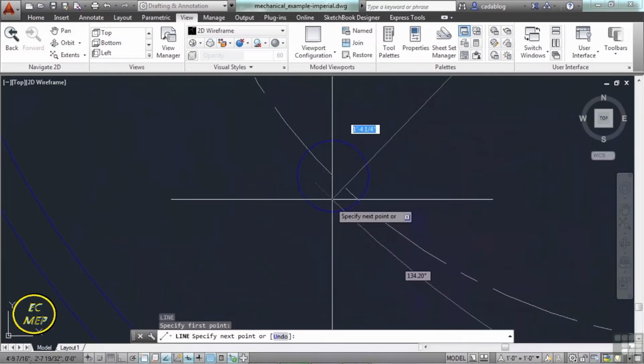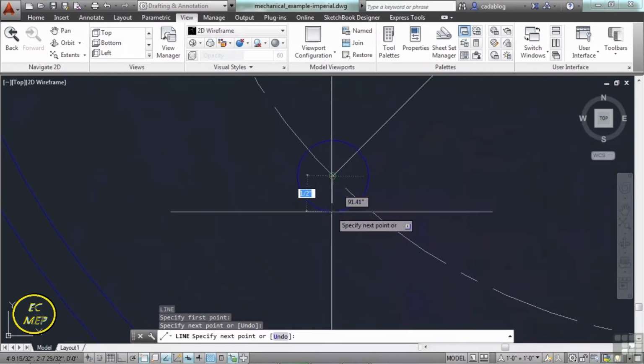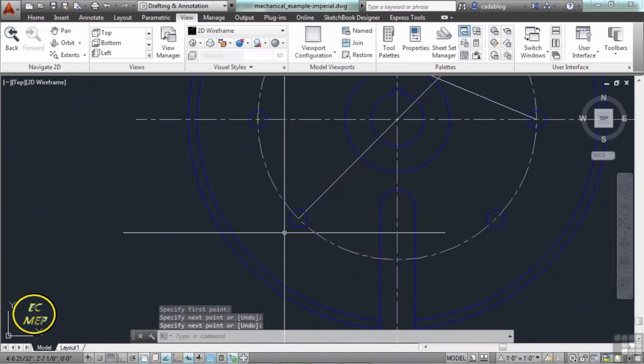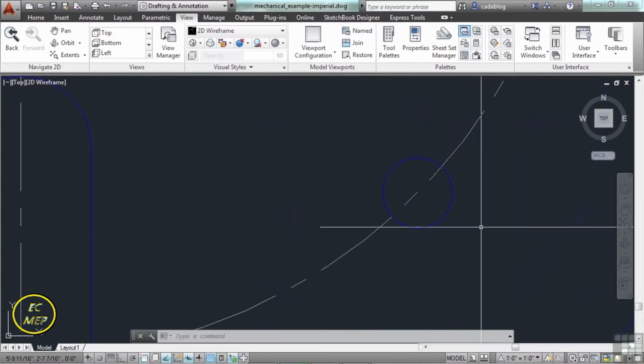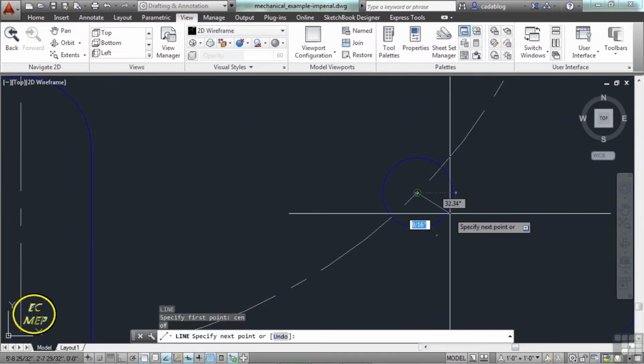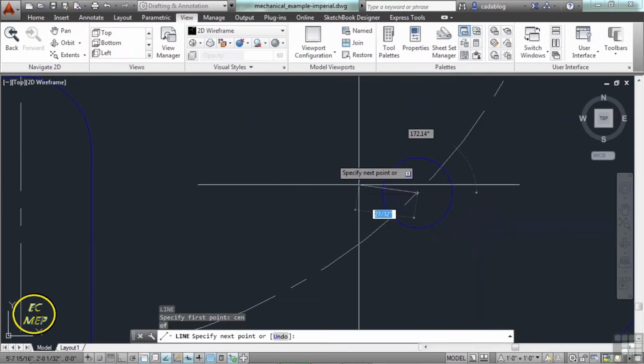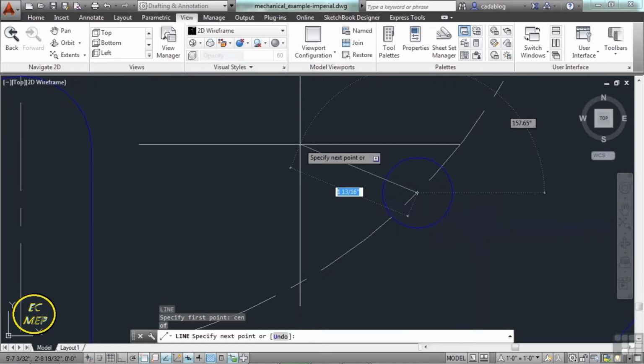These are transparent commands. And ever since the scroll wheel became used in AutoCAD to zoom in and to pan around, I haven't really used transparent commands or thought about them in a long time. But if you're entering your commands on the command line, so if I'm starting off a line, snap to the center of the circle, and I want to enter the zoom command, I have to use an apostrophe.